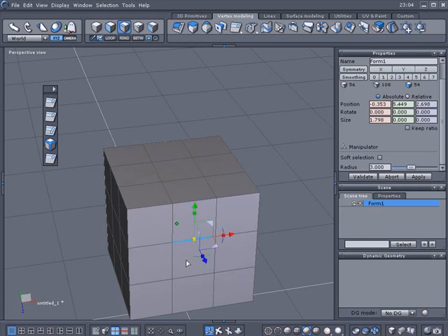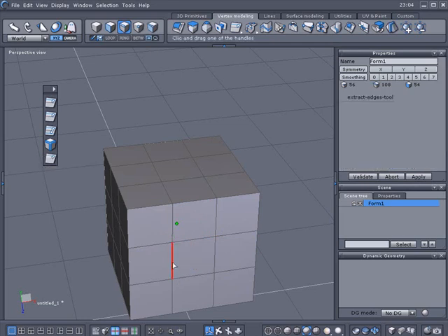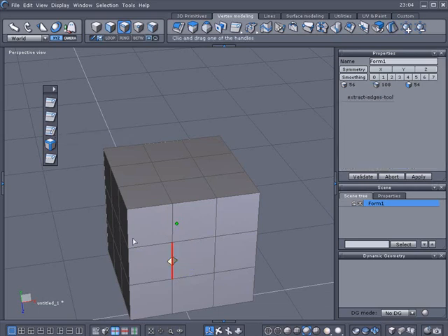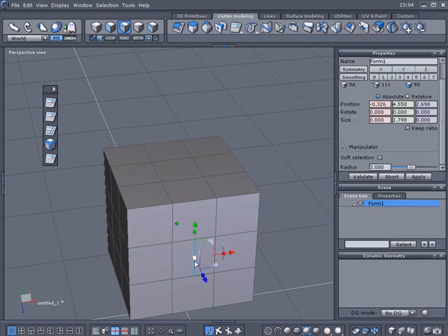It'd be common to use this maybe somewhere in the center of an object rather than in the corner up here as I did. As I can select it over here and move the edge over here. We'll Control Z that. Alright, we'll start with the extract the long edges. So I'll extract here and I'll move it over here. As you can see, it almost worked like the move edge along, but it just, like it said, it moved along the edge over here. We'll Control Z that.